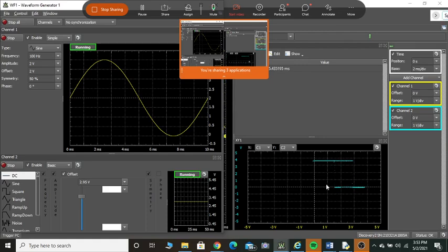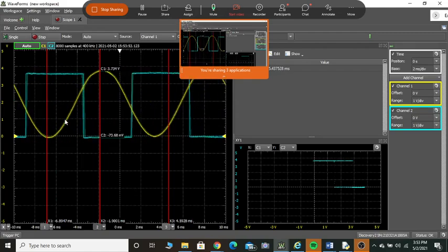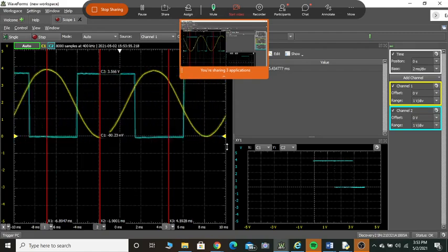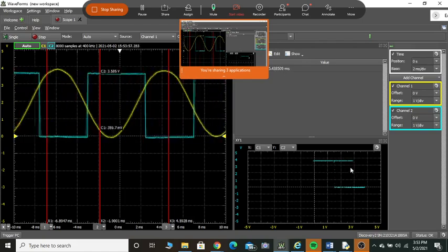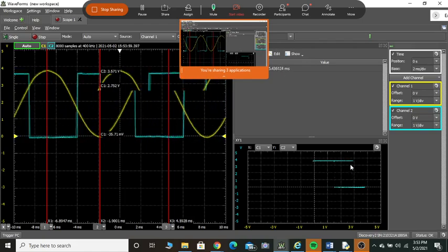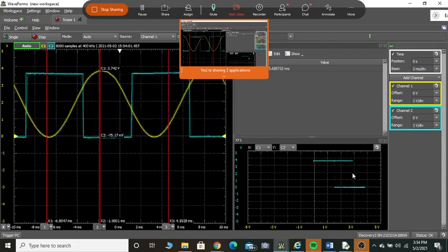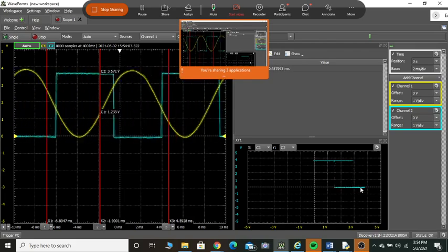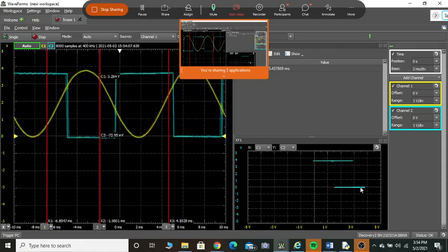This way VTH and VTL. So this is what we have done in the class also. We have seen that this output is always a square wave. This is like an inverting Schmitt trigger. If the input voltage exceeds VTH, output is going to minus Vsat. Minus Vsat in this case is zero. Correct?